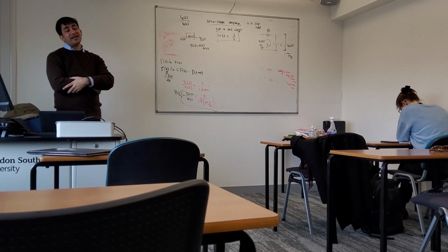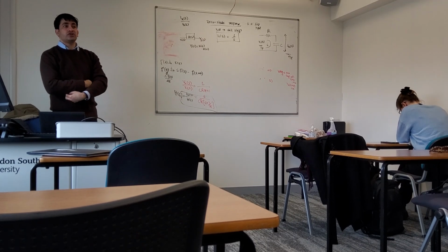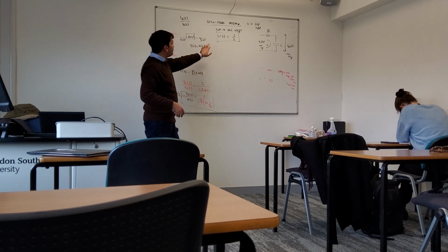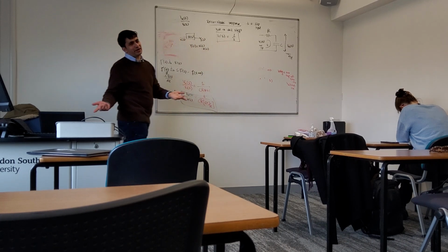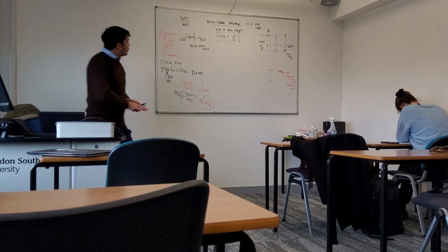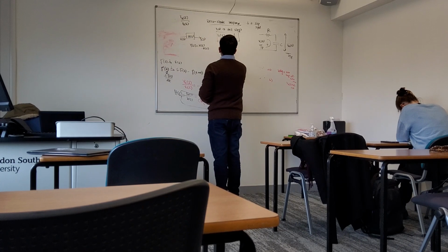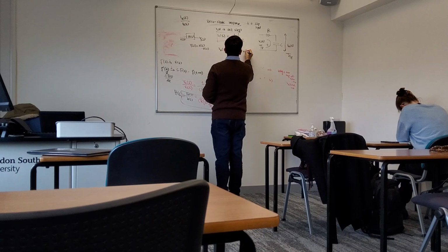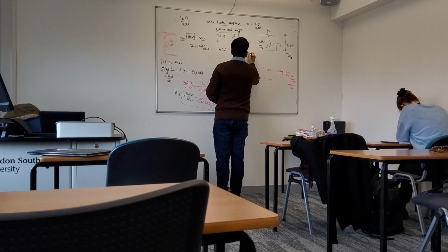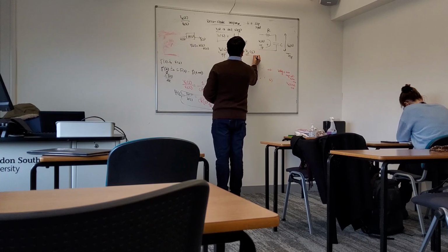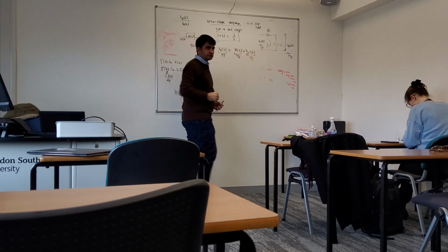But I cannot solve easily in time domain. So the best thing was to take this transfer function, multiply it with a step, and then take inverse Laplace transform, right? Simple. Okay, so I need to find V2 of s, which was H of s times V1 of s, output equals transfer function times the input.